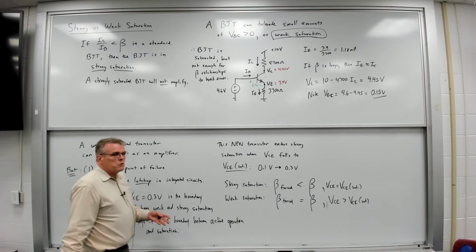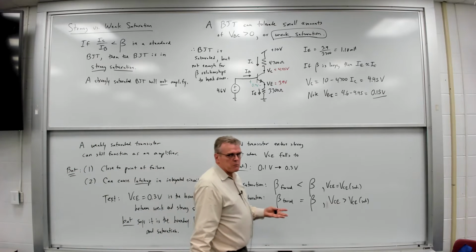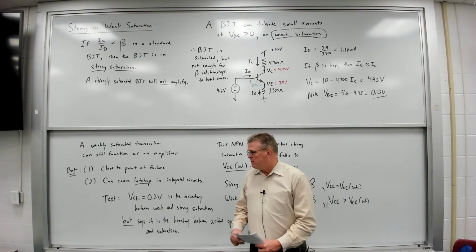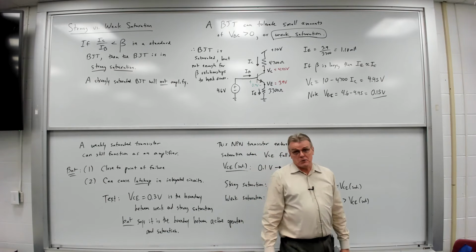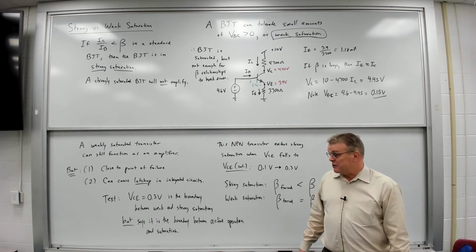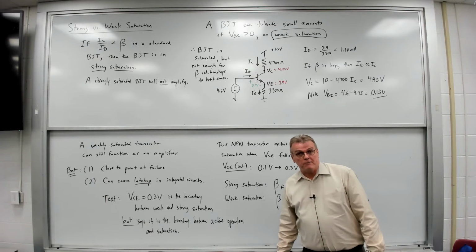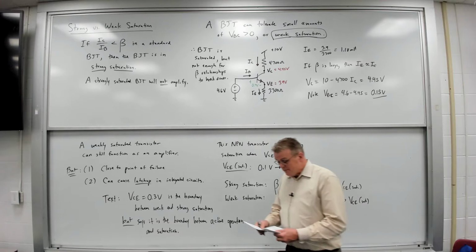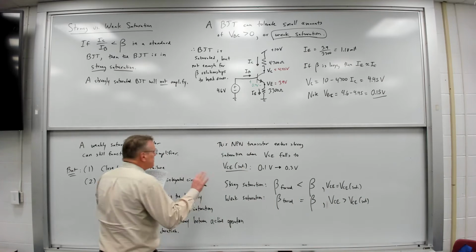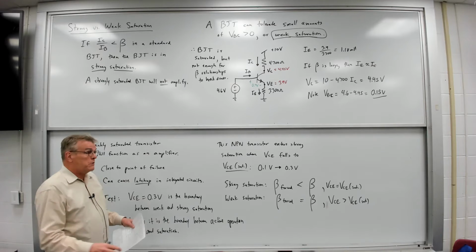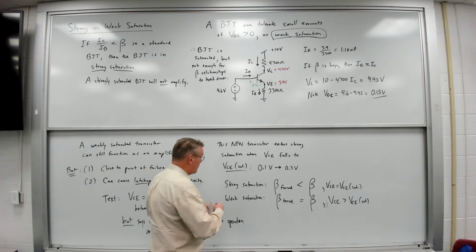It considers, as long as the beta relationships work, it considers the transistor being in active operation. But many other people will totally disagree. They'll say it's weak saturation, and they'll also say never bias a transistor in weak saturation. All right? Now, once a transistor is in saturation, and by that I mean strong saturation, there is a circuit model we can use for it.